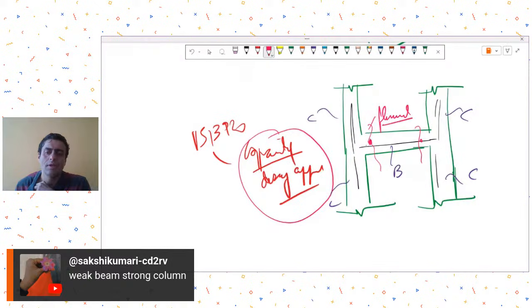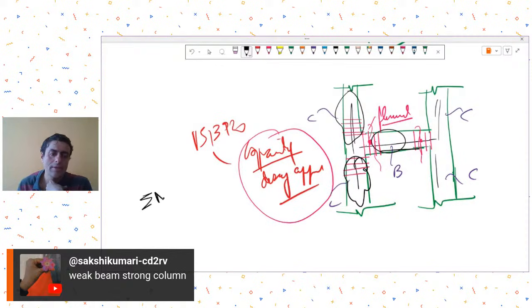In shear, if you remember, we are designing against any shear failure, brittle failure, by providing confinement reinforcement, closely spaced rings, by designing this beam for capacity shear and all those things. Now, to avoid the failure in my columns, I am deliberately increasing the moment capacity of columns with respect to beams. So that means if at all a failure has to happen, let it happen in the beam in flexure rather than in the columns.